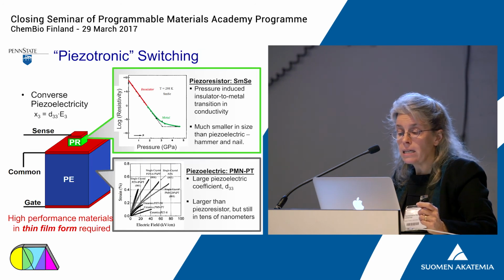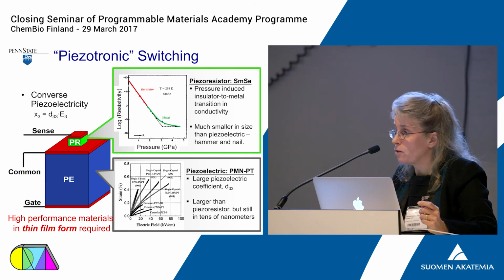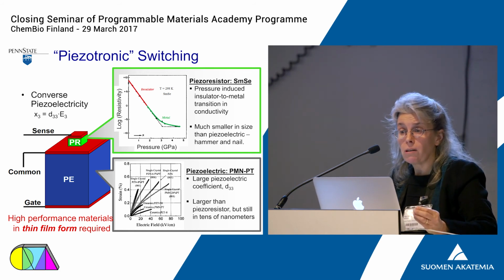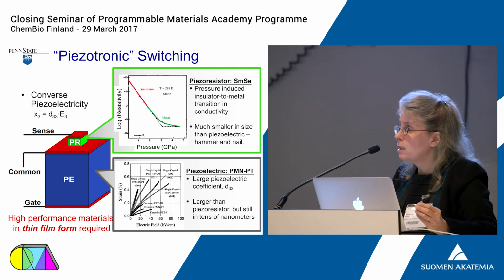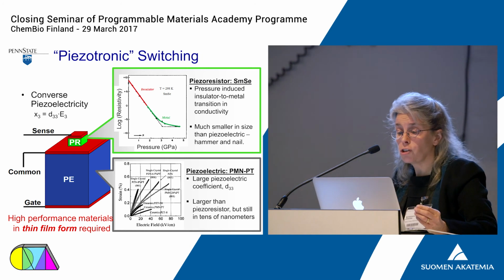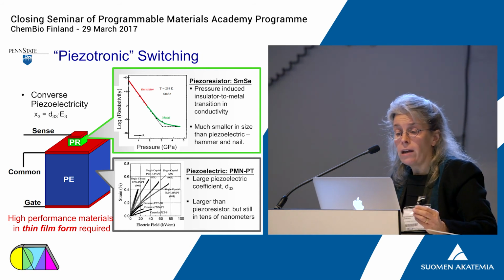We use lead magnesium niobate-lead titanate. Here's that strain compared to a material like lead zirconate titanate. You can see the slope is very much larger, so it's much more appealing for this application. For the piezoresistor, we use samarium selenide. Samarium selenide undergoes an insulator to metal phase change continuously as a function of pressure. The mechanism for that is shown here.